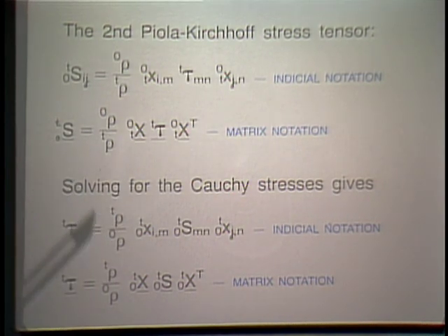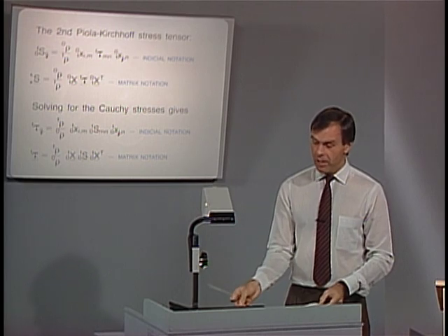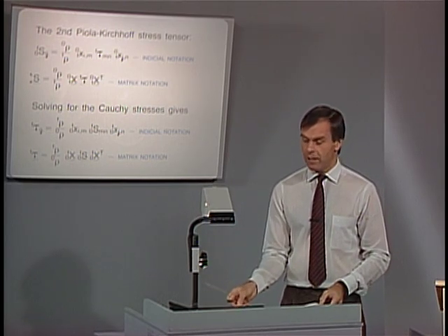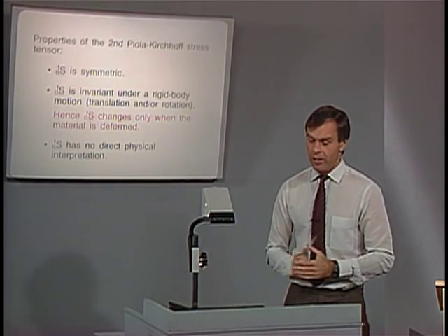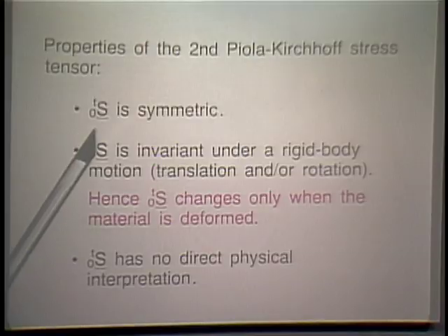Well, these are relations that we want to keep in mind and that we will be referring to quite abundantly later on. Let us look at some properties of the second Piola-Kirchhoff stress tensor. First of all, T0s is symmetric.